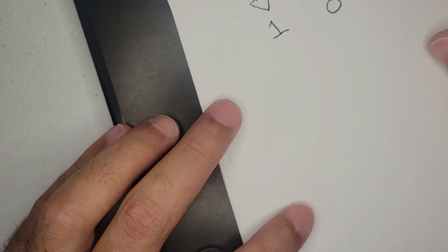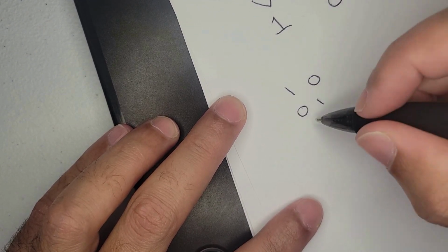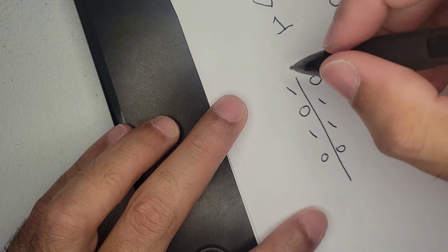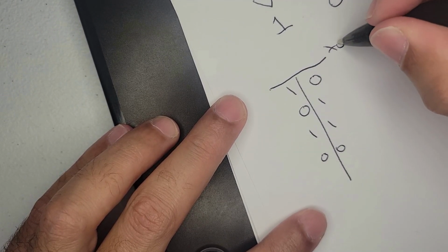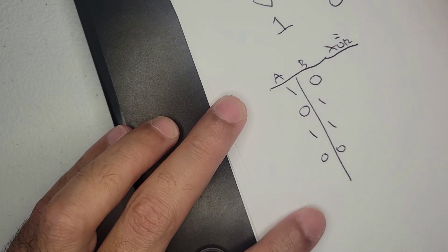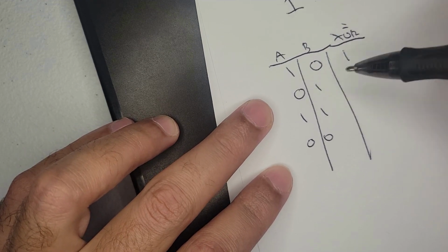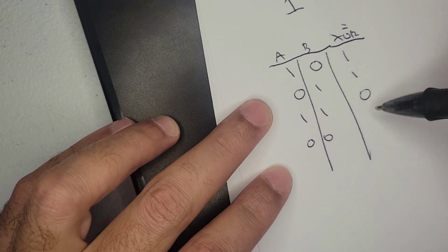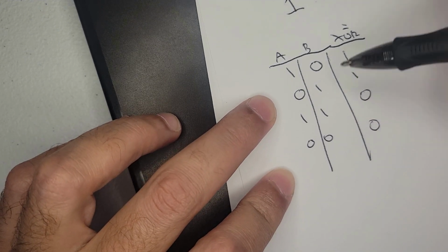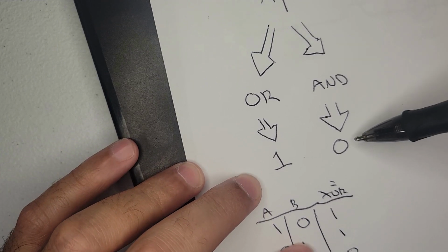The reason why is if we look at all of the possibilities: 1, 0; 0, 1; 1, 1; and 0, 0. If you remember, the easy way of figuring out the XOR result for A, B is: are they different? Yes. Yes. No. No. So that's a shorthand way of doing it. But this is the way that we actually build that logic.